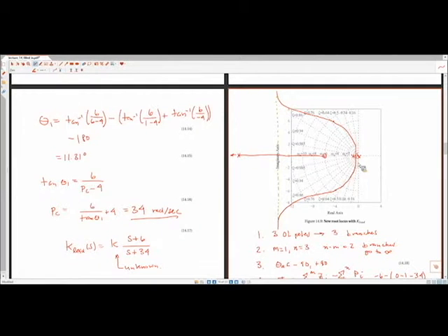But this is going to be our new root locus plot. I talked about there were a lot of questions about design, and we were just talking about root locus plots itself before we got into that design. I said, okay, we're going to morph the root locus plot to be more desirable. This is exactly what I'm talking about. We've significantly changed the shape of the root locus plot by adding poles and zeros.